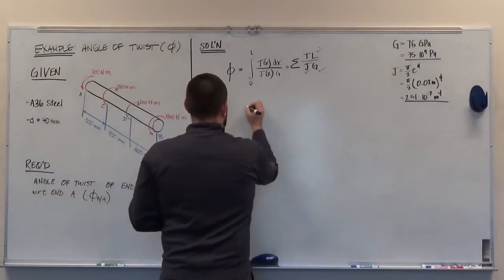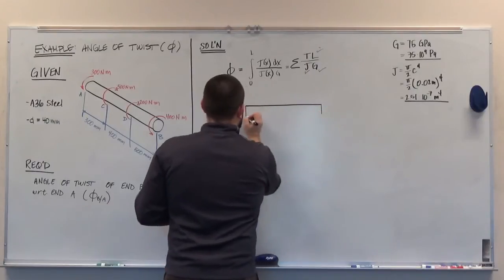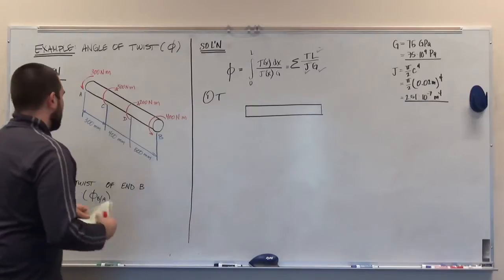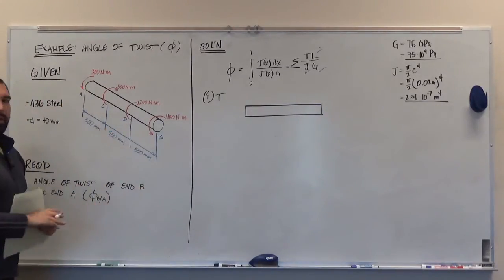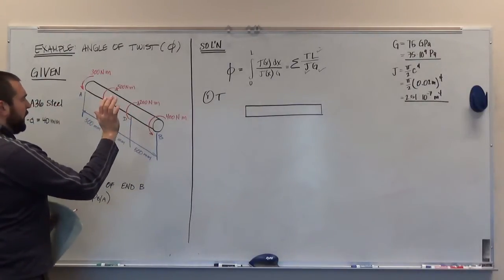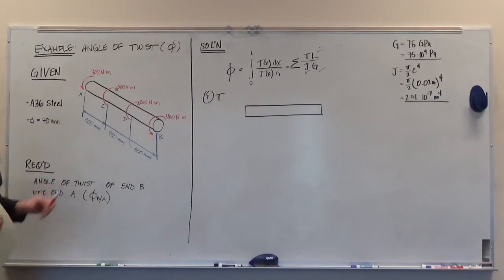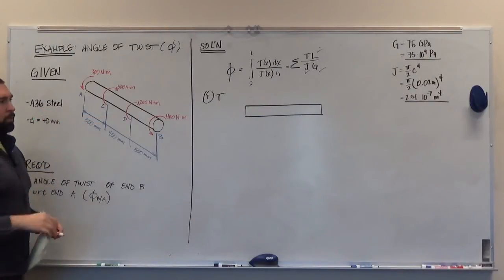So all that we're going to do in that situation, we're going to draw the shaft in 2 dimensions, and I'm going to start drawing each of these moments on here as 2-dimensional vectors. We use the right-hand rule for that, so we take our fingers on our right hand, we rotate our fingers in the direction of the rotation that's indicated on the 3-dimensional isometric view, and then whichever way our thumb is pointed, that's the way the vector should be pointed on our two-dimensional plot.